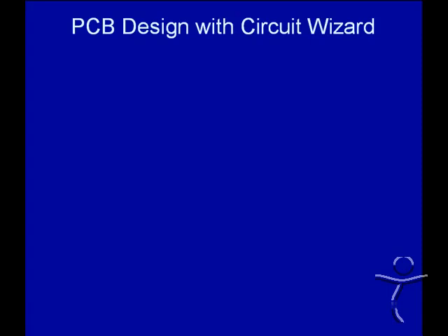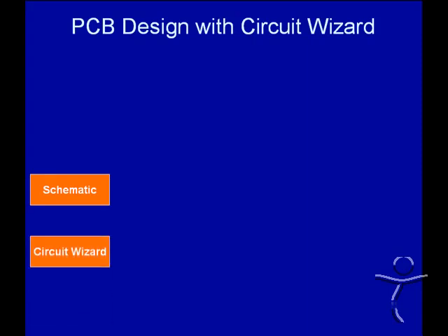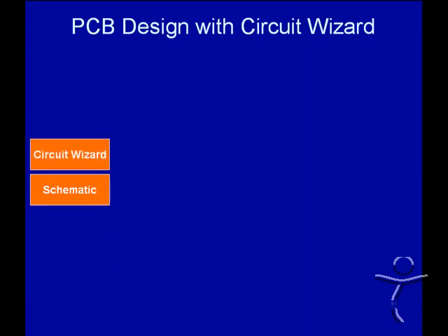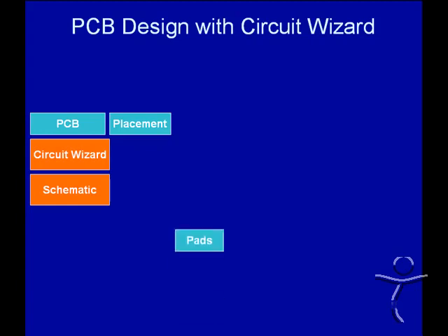So in summary, our PCB manufacture with Circuit Wizard has several steps. We first define a schematic with Circuit Wizard. We then do our PCB export. We place our components and tracks either with auto placement or the manual routing, using the highlight rat's nest as guide to placement.